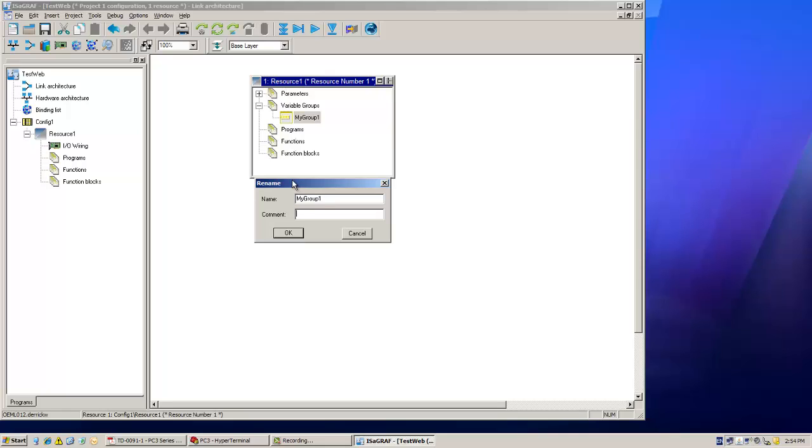under that variable group. In order for a variable to be exposed in the PC3 web interface, it must have the word web at the start of the comment field. This can optionally be followed by 4 letters, W, R, or N, indicating write access, read access, or no access respectively for each of the 4 users that are available to be customized in the PC3 web interface.